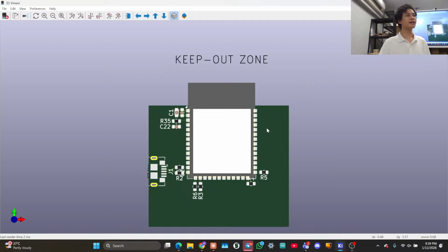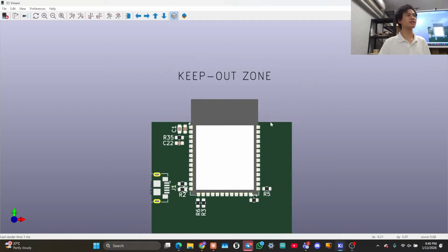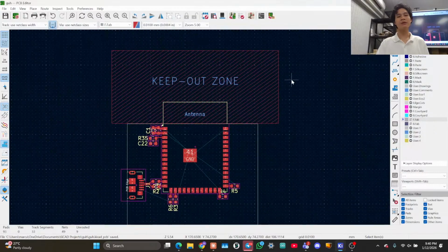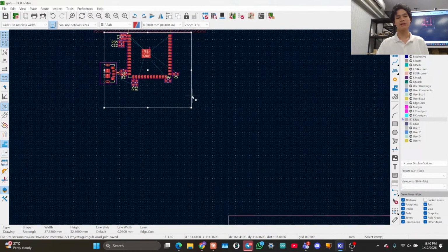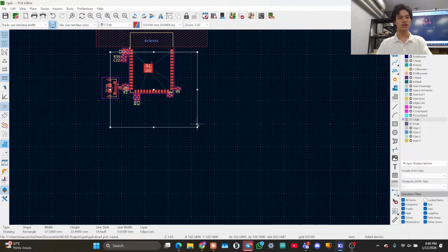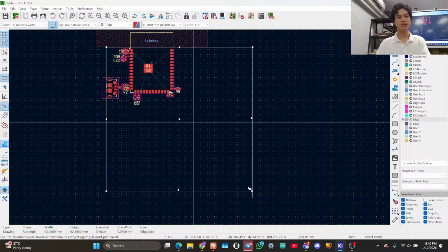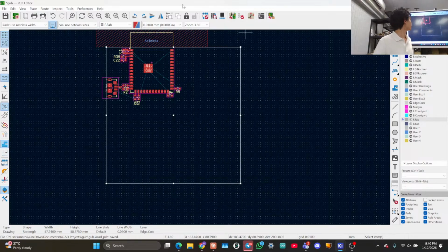Theoretically there's no reason not to extend the board further, but you can't do anything with the extended part because you can't have copper there. If you have copper there, it interferes with the electromagnetic properties of the antenna. So we just end the PCB here. Fair enough? But we can play with the other two sides of the PCB. So I can make this as big as I want, as long as I don't change the left and top side. Okay. All right.